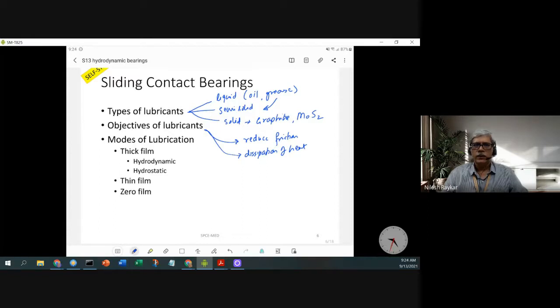So when you say that viscosity is giving you the load carrying capacity, the viscosity also introduces friction, and you have to overcome that friction, and as a result, heat will be generated, and that heat will be carried away by the lubricant when it is getting depleted. So you have to continuously supply the lubricant so that the part which is getting removed or leaked gets replenished, and that leaking fluid removes the heat.